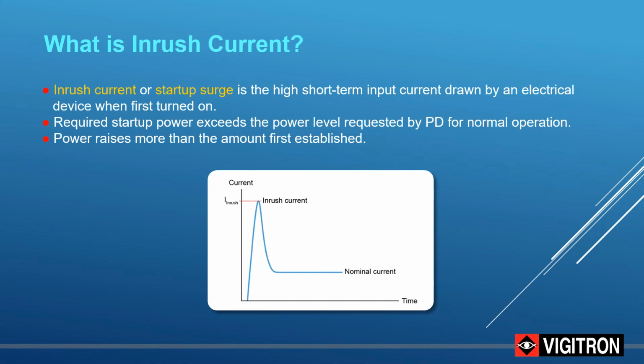But there's two aspects when we talk about something related, let's say, to an IP PoE camera. Basically, not only is more power required to turn it on than to maintain it, but many, many cameras today, if not all of them, have some form of what we call an accessory feature. That could be day-night, that could be PTZs, that could be LED turn-ons. And that power is approximately 20% more than what's usually called for within the specification. That's why understanding how those specifications are expressed becomes a very important element in the design of your network.